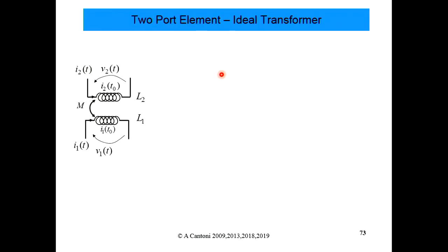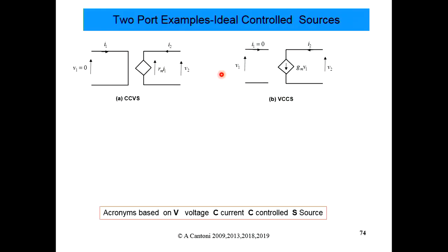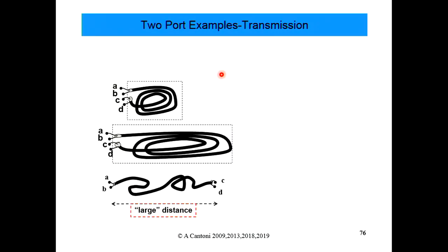So we looked at two-port elements. Now, a lot of the course we're going to look at a two-port model for transmission lines, okay? And the main things to remember, if we can actually make a two-port model of something, is that a particular port has two terminals, and the main thing is we have to be able to assume that I in equals I out, okay.